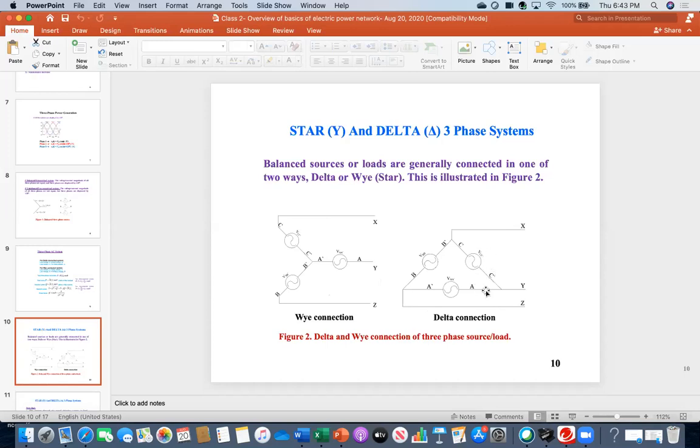Now come back, Manoj and everybody. For example, there is unbalance in this case. As I told you, the impact of unbalance is that there will be additional circulating current, and that will flow between phases. So in this case, where will the additional current go, because there is no neutral path? What happens in real practice is that those additional currents start flowing through these coils, but they are blocked because there is no neutral path. Here there is a neutral path, so it went until the ground. Here there is no neutral path, so they just get trapped, they just get blocked.